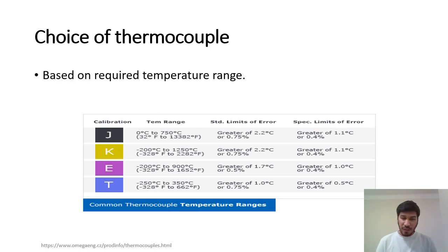If you use a K-type thermocouple, which we are going to use, and which I use for machining experiments with titanium and Inconel, it is because at high speeds the temperature is almost close to 1000 degrees Celsius. That is in a dry condition; with coolant, it's lower.